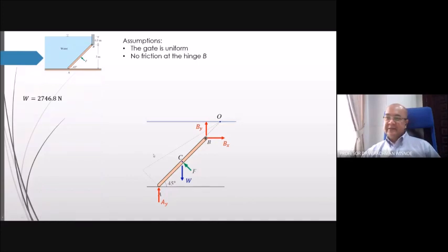This right triangle represents the pressure distribution. The pressure distribution is only valid from A to B. So I draw the pressure distribution on the gate AB. From here, we can calculate the resultant force, Fr. The Fr is applied at point B, the center of pressure. The Fr itself, we call it the resultant force or total pressure.